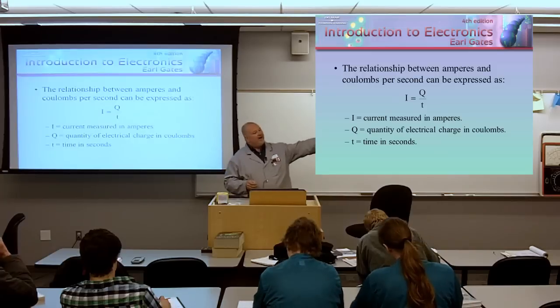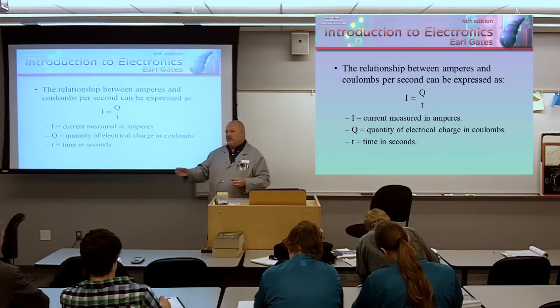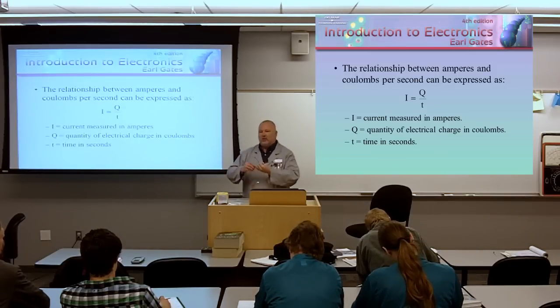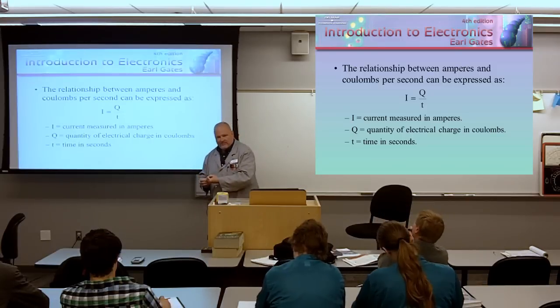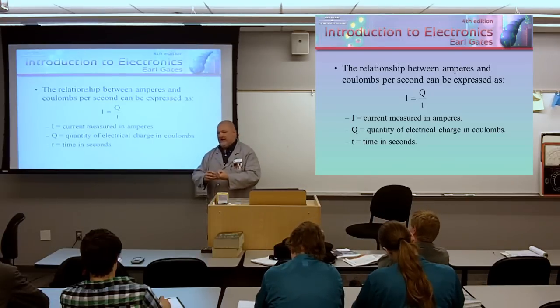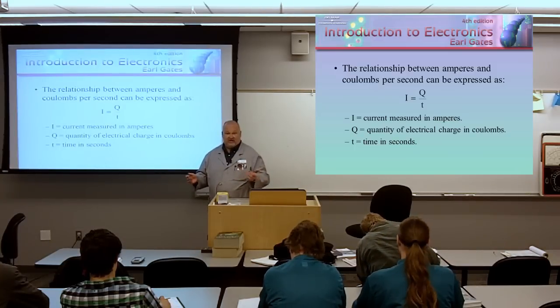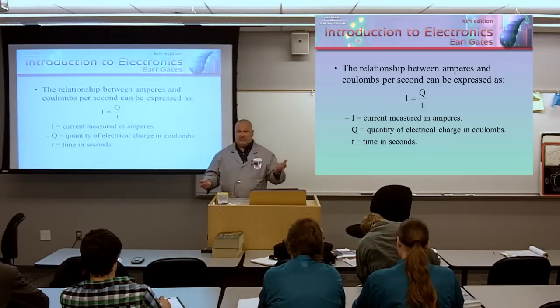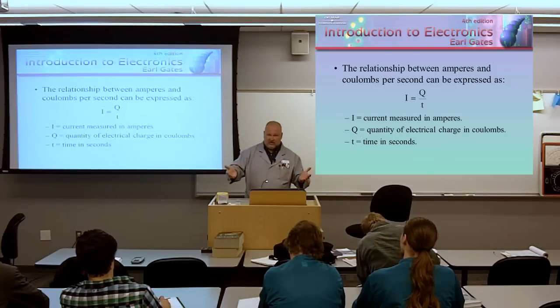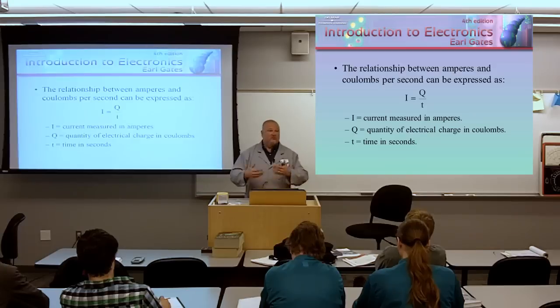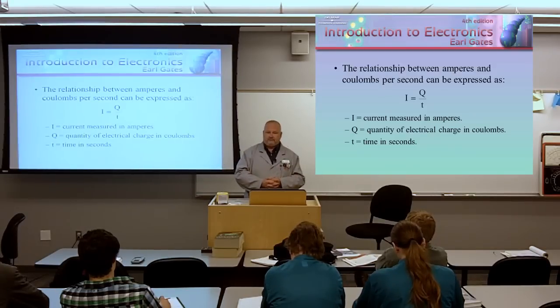Okay? From that box, the circuits in your home get distributed to circuits that are typically either 15 amps or in some cases 20 amps. And for some of your appliances, you know, they'll be a little bit higher in some cases if you have an electric hot water heater or things like that. I've got a hot tub, okay, it requires more than 15 amps, more than 20 amps, so I've got a high current connection going to that.